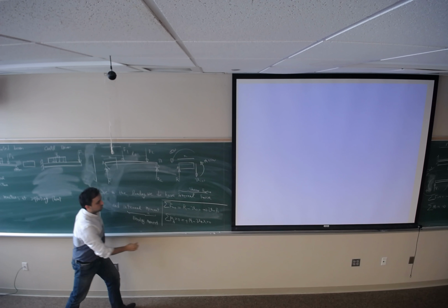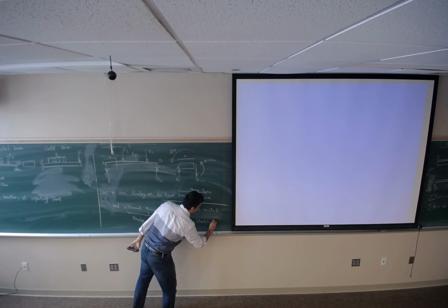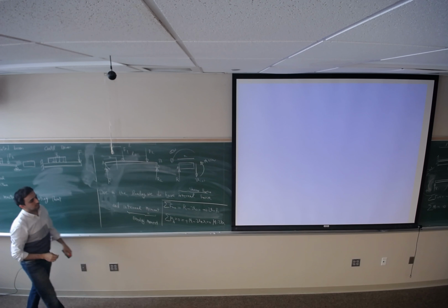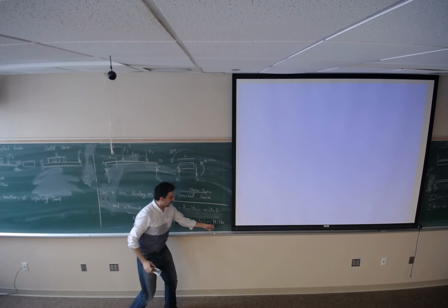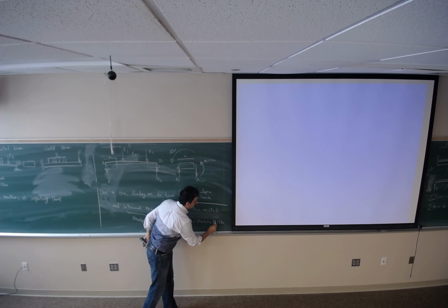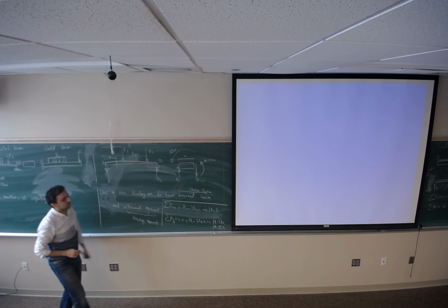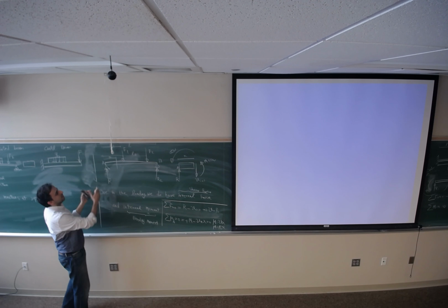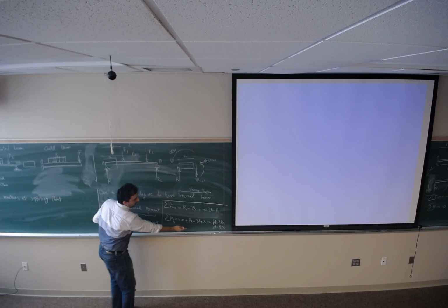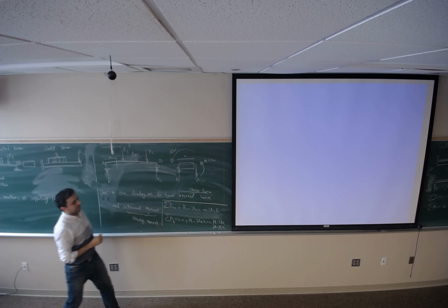So M is going to be V times X, and V you could find up there, so M would be R1 times X. So the bending moment here varies with X in a linear relation.